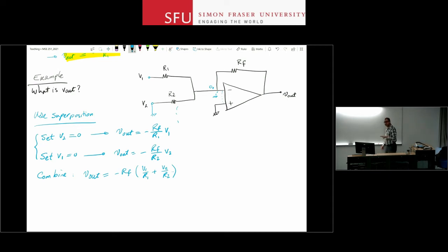Okay, so what did we make here? Right here in front of you is an analog adder. And the good thing about it is that it's a weighted adder. So you can combine multiple voltage signals that may come from different sources. You can give weights to different voltages according to your requirements, and add them up using this circuit. It's an analog adder, right?